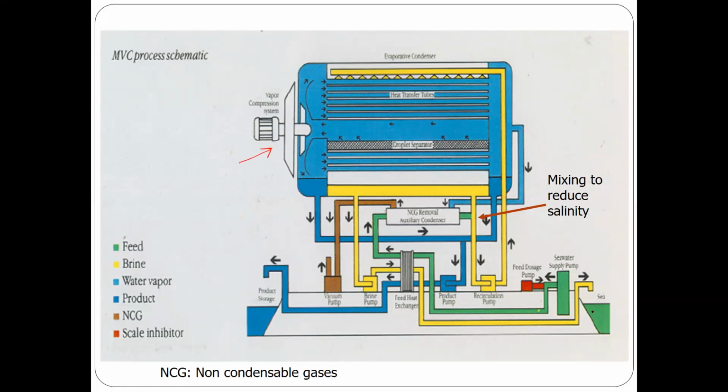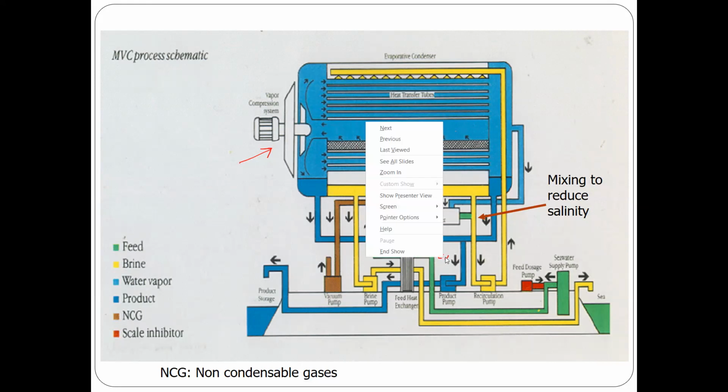Seawater is coming following that green color here. So seawater is being taken. There is a seawater intake feed pump, and the seawater is going, if you are following the red dot on the screen, into a heat exchanger. Here we have a single heat exchanger where we have 3 fluids. They are not mixed together, of course. One of them is the seawater in, the green one, and this is the one that needs to be heated from T cooling water, its initial incoming temperature, to a value that we call T0.